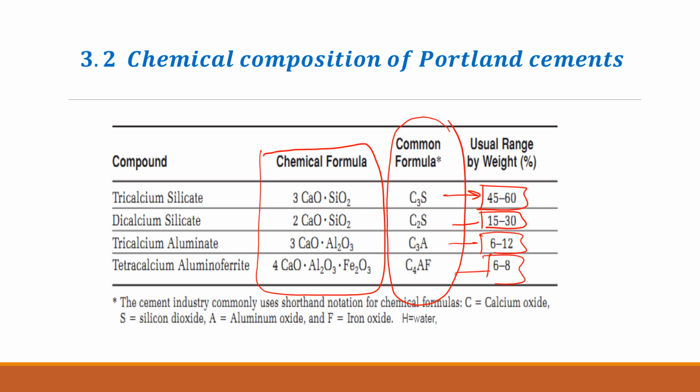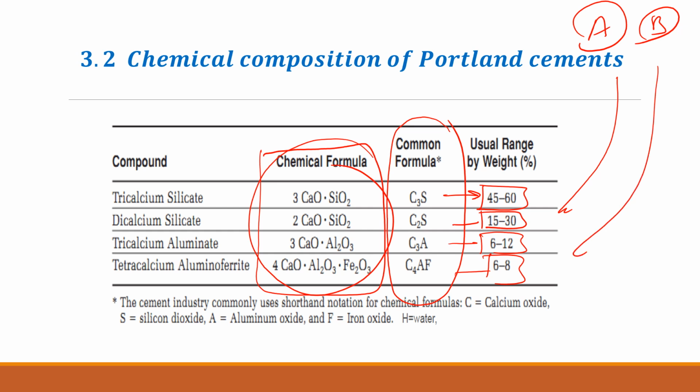By burning limestone and making it clinker and grinding, we get all these oxides together. So it's happening due to the reaction. So we can't control much the process. So we get all 4 ingredients in a cement, but in different proportions. For example, if you consider A and B, these two have different compositions of these 4 compounds. Makes sense? We can't say every cement has the same amount of C3S. It can be different, but ranging from 45 to 60%, roughly. Are we good? Any question?